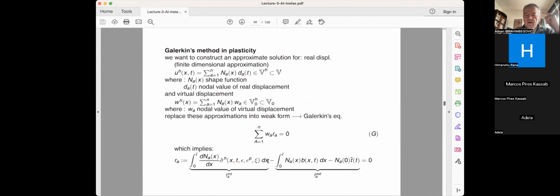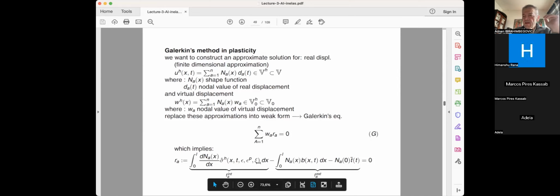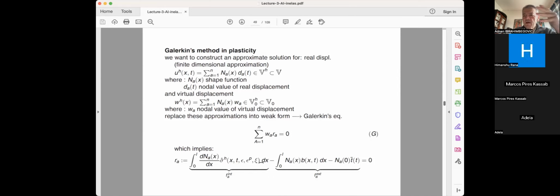And we can really recognize the advantage of numerical integration, not only for simplifying the constructing of the arrays that are needed for each family of the elements that are the same, but also for plasticity. You'll see that in a moment, in the sense that the information for the plastic strain and internal variables is only limited to a certain number of points. I don't need these fields everywhere. I need it only for particular points.